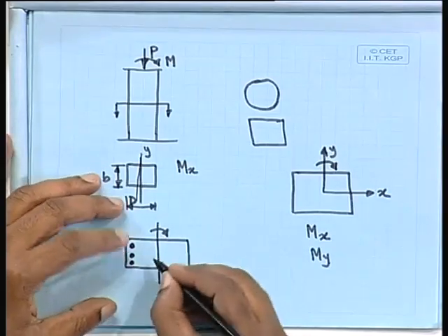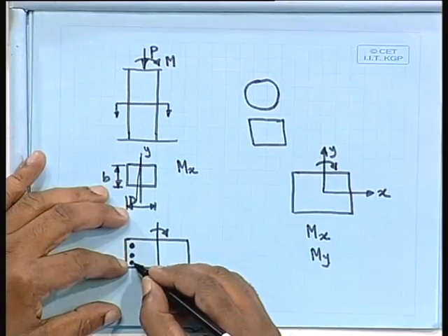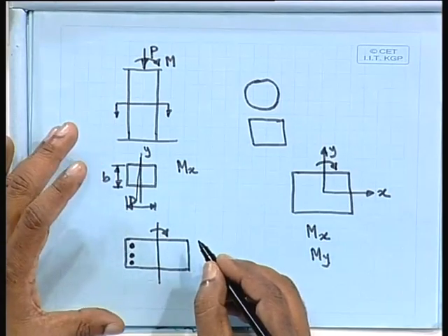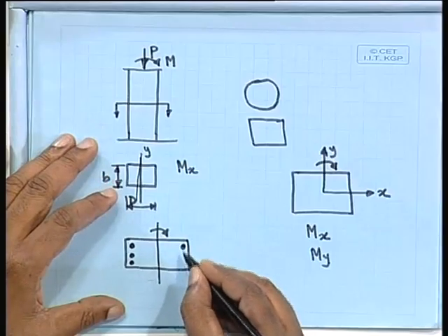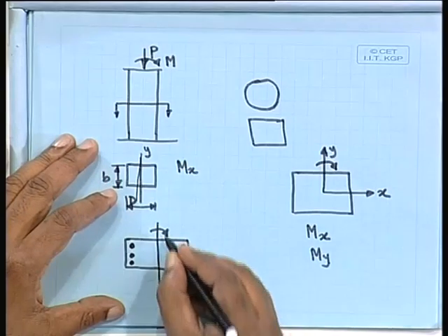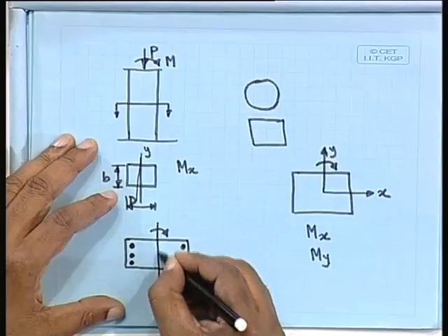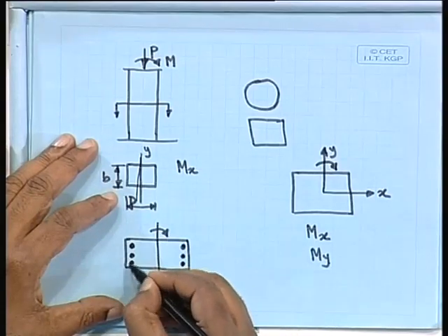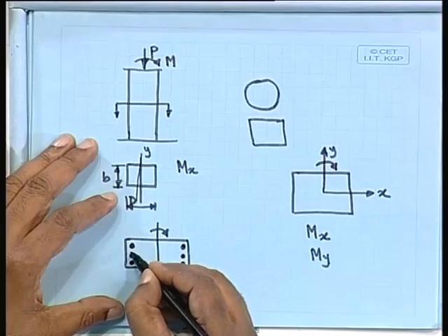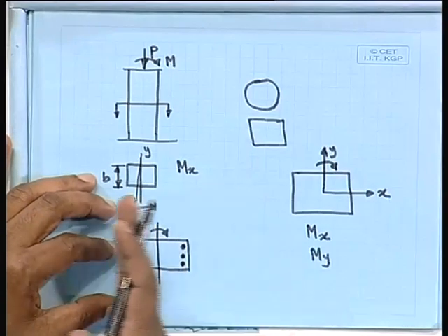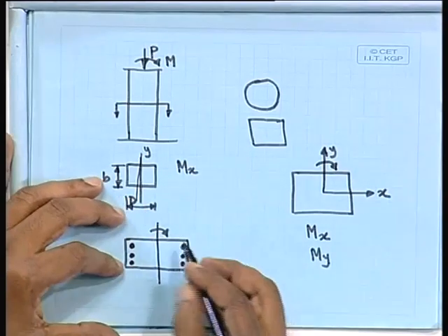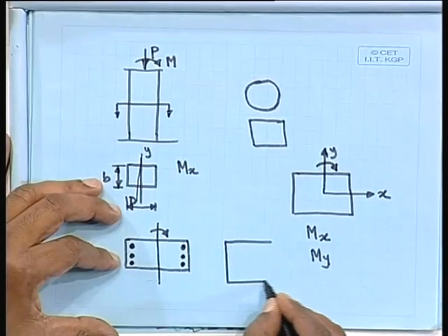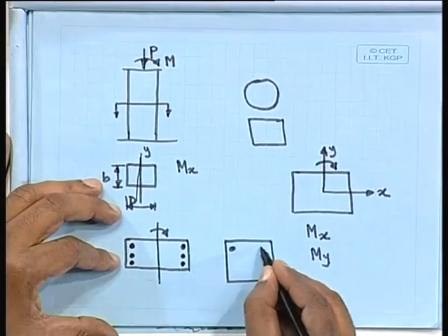So far as axial load is concerned there is no problem wherever you put the reinforcement, but so far as the bending moment is concerned, since this moment acts about this axis, we can provide the reinforcement here, either at this end and the other end. Alternatively, if required, we can specify the reinforcement all along.